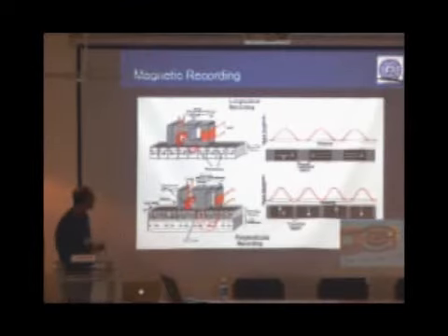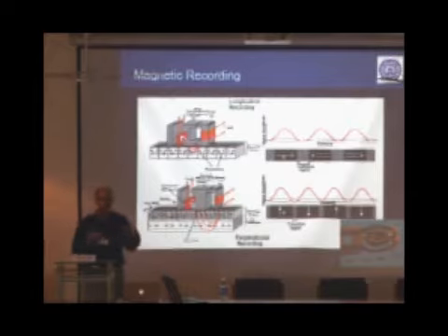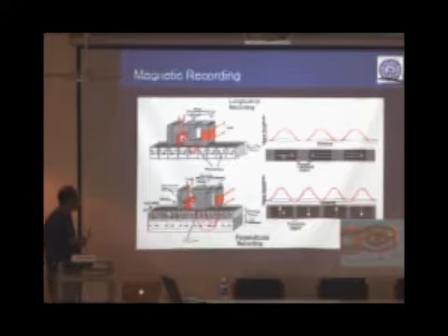There are actually different ways of storing data. One is called longitudinal, another is called perpendicular recording. The reason I'm showing this slide is that as you store data longitudinally, the bits have a very high demagnetizing field and they don't like to point head on, and it is better to have them aligned perpendicular to the plane of the medium. So perpendicular recording allows you to go to much higher storage densities and also slightly faster read-write access. However, it has its own problems in terms of how the head and the media are designed.